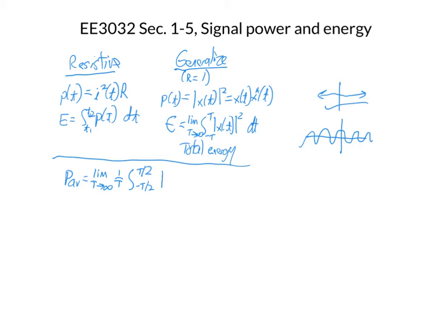And like I said, we're taking the energy, so any expression for energy will work. If I have a complex signal, I will use the conjugates, but we're not really dealing too much with complex signals in this class. So most often we'll see this magnitude squared approach integrated over time. So that's the definition of average power, and it would work just fine for that sinusoid or that DC value on the right, or more complicated signals. And if a signal is periodic, I can make a simplification.